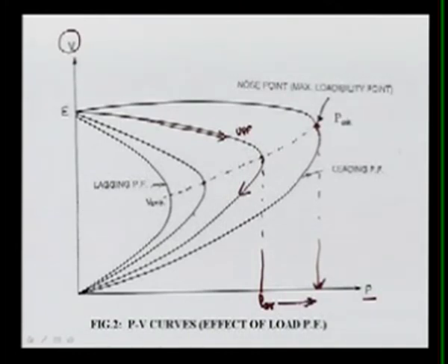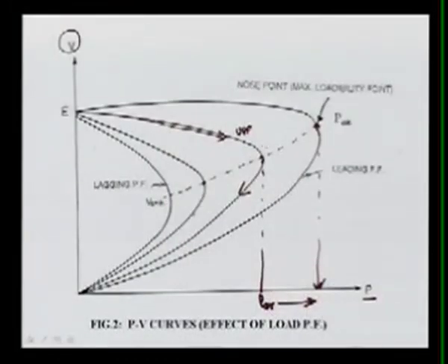So this shows that if you improve the power factor of your load, you can load your power system without losing stability due to voltage. Because if your power factor is increased, we have gained this much margin, and then you can consume more power.